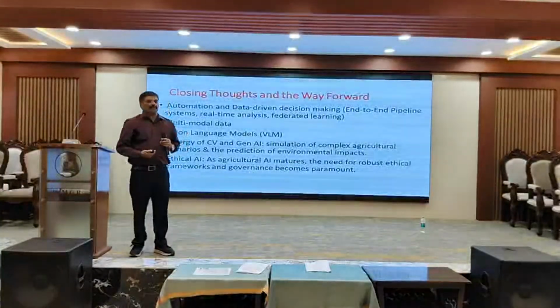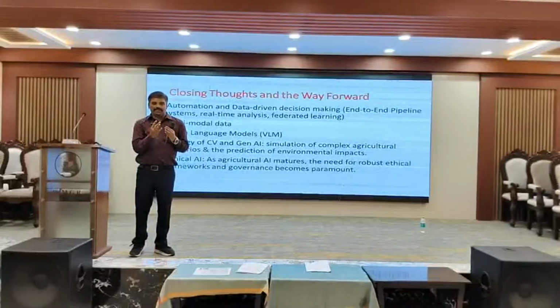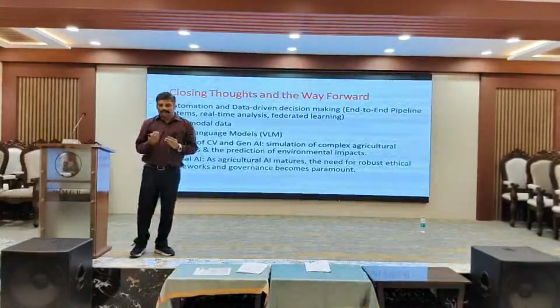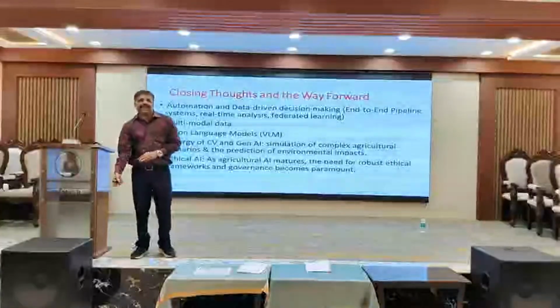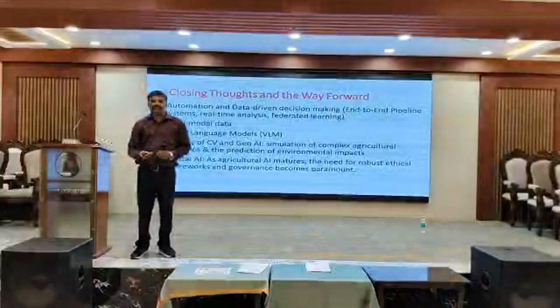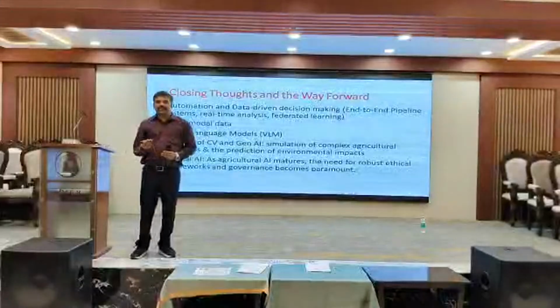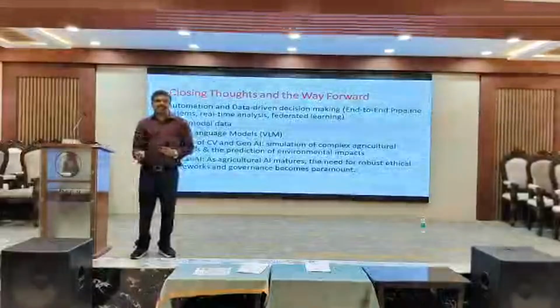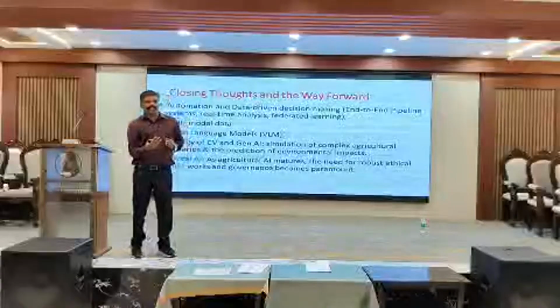So multimodal data. Whatever I have talked about so far with images gives information about surface damage, in the case of fluid structure. But anything beneath the slab, because the slab is about 100 mm thick, if there is a crack in there, an infrared camera will pick up the wavelength difference. So you will get more information up to a certain depth. So infrared images come into play.